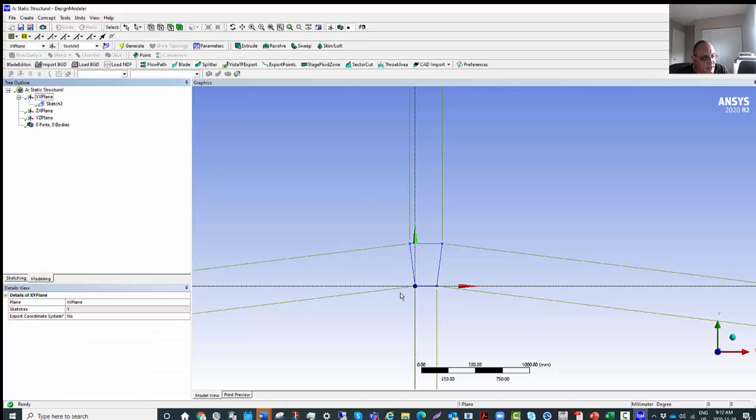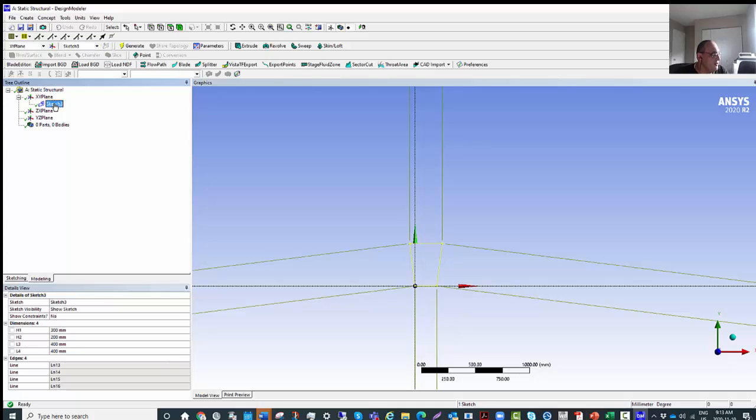Hopefully this works. Of course, one of the things in solid modeling, I guess you guys might know, is that if you want to extrude or do solid modeling, the shape needs to be closed, and the same thing for finite element. So let's see if this is closed or not.